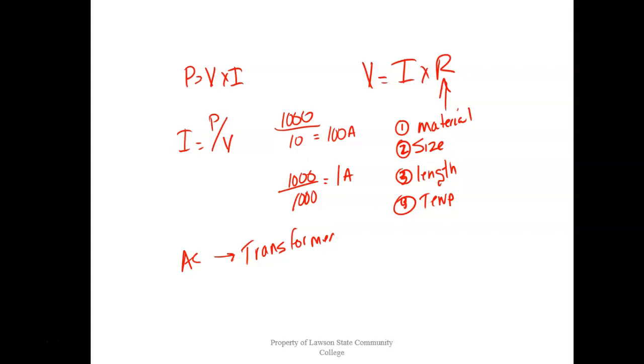But the closer we get that down, guys, sooner or later we're going to go back to copper. When the voltage starts going down, the current is going to have to go up to deliver that power, right? You understand that? So the closer we get to us and the lower the voltage gets, this is why your house is wired with copper. They tried it with aluminum one time. And they burned down a bunch of houses.